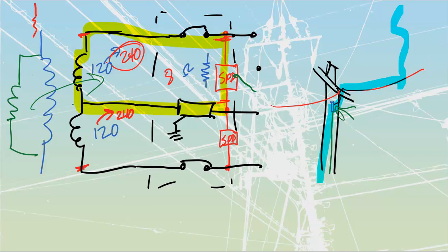But it is going to be a semiconductor component that is going to trigger. We build these things specially. Once we bring these up to a trigger voltage, they're going to go into conduction. It is not a resistor the way that thyrite is. It's a semiconductor that's just going to drop its depletion region at that point. So it will wait till we hit our value of voltage. If this was what it was over here, we could think about this thing as if it were back-to-back diodes in a lot of cases.